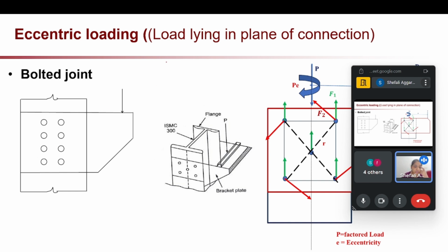So these are the different types of welds and how we have to design them. Next is the eccentric loading. Eccentric loading means our two plates are joined together but loading is not on the plane of our plates. If we have two plates connected and this is our CG point, if our load is acting on this point, that is our normal stress. But if our load is acting on some other point at a distance e from our CG point, then that is called eccentric loading.